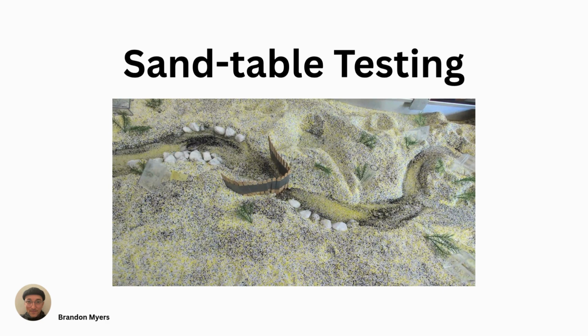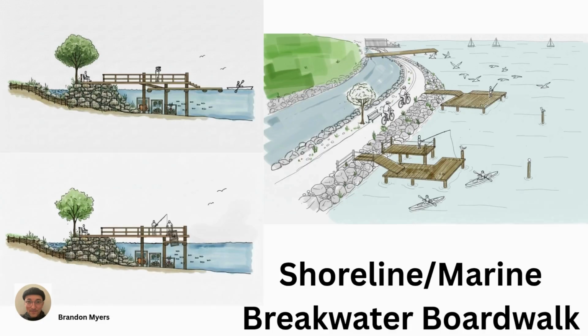Our design for representing a culvert was not restrictive enough to divert water to the retention pond during flooding events. The material representing soil in the sand table was more buoyant than we had expected, which led to challenges with predicting how the sand would react to our test. There was much more groundwater flow rate than we expected as well.